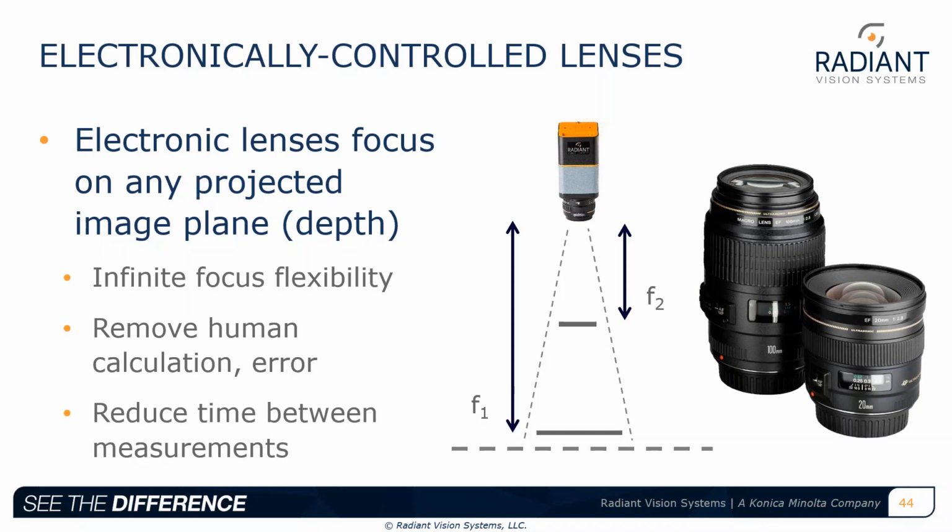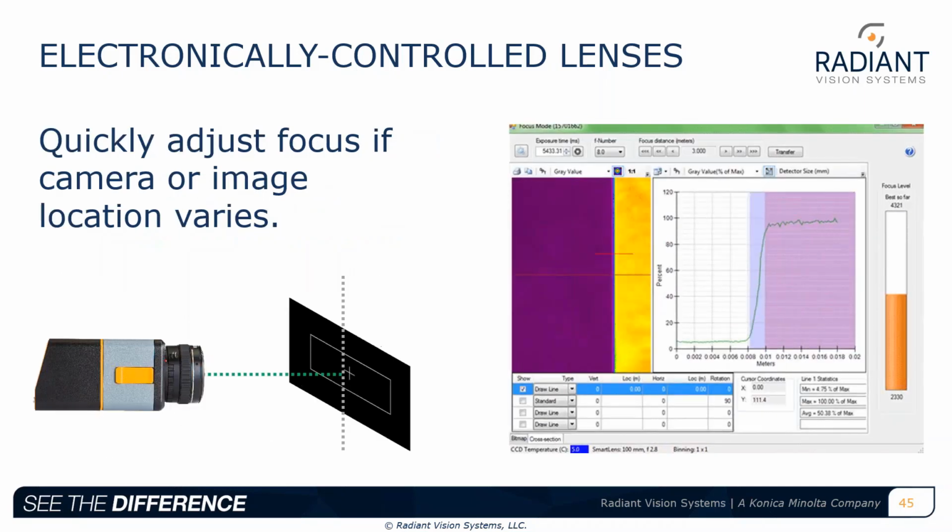This allows us to adjust things like the working distance for focus and adjust the depth of field to mitigate any issues that we might be seeing in characterizing information in the head-up display at varying distances. A big aspect is removing human error from a calculation perspective, but also reducing any type of manual-based projection or verification information from characterizing distance.